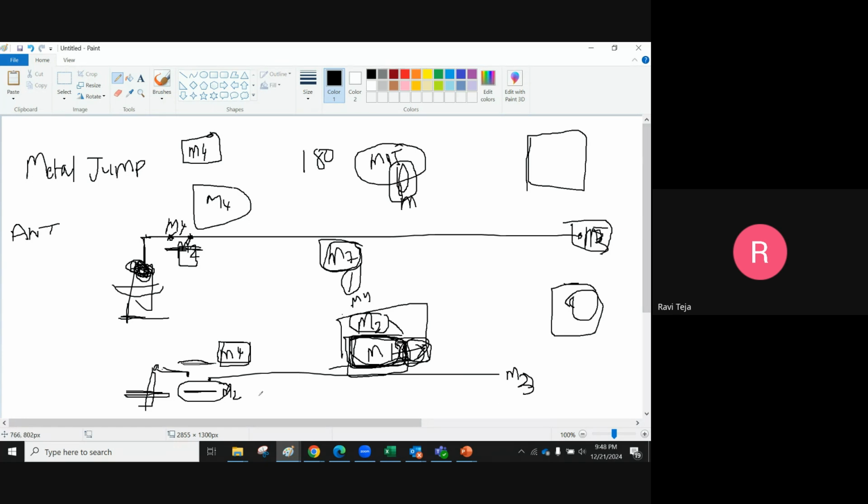Okay, I will tell you the reason. The reason is, this is M3 and we are having antenna on this, right? If I go to M2, now practically what's happening is, this is M3. First I have chopped M3. I chopped, and here I am going to M2, and then there are vias, M2, M3 via, M2, M3 via. This is connected to the gate.